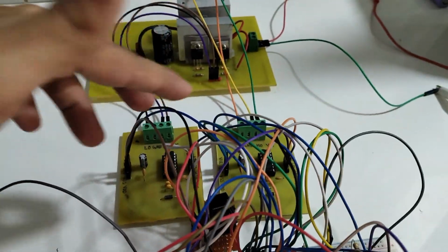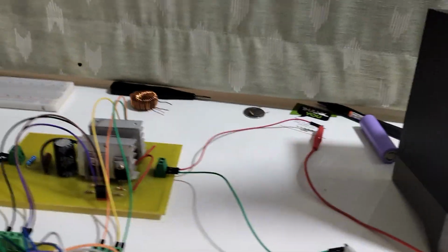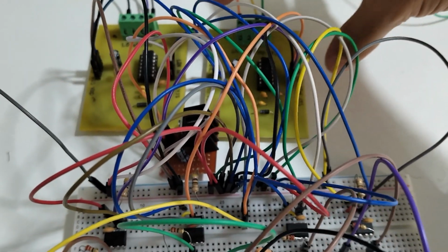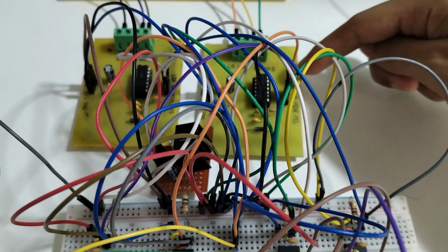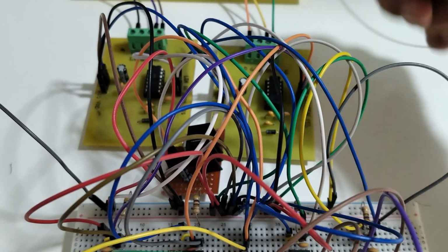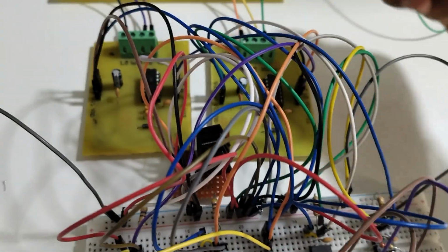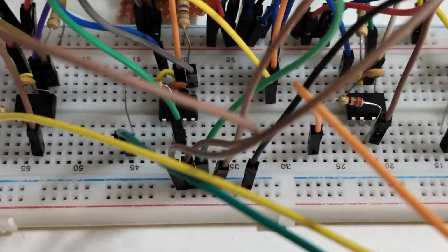The H-bridge board, the two drivers remain the same, but earlier what we did was we gave parallel outputs to these, right? That means the LN of this is the same as HN of this high side, and LN of this is the same as HN of this. So that's what we did last time, right? What we do this time is we independently control all four channels. That's why I have added two more optocouplers. Earlier, there were only two, right?